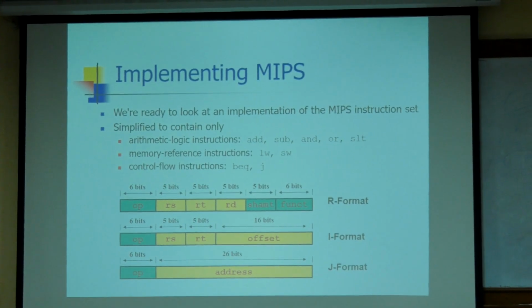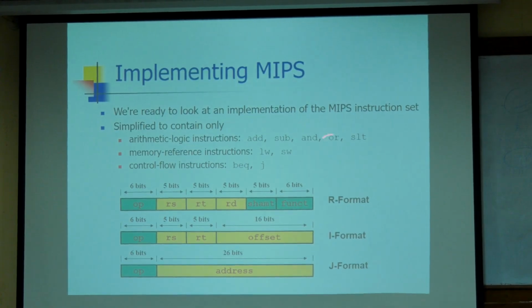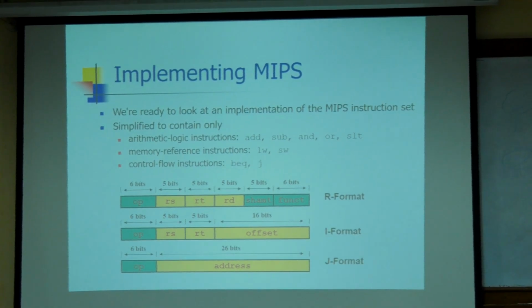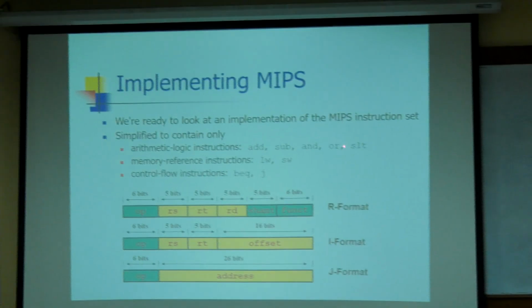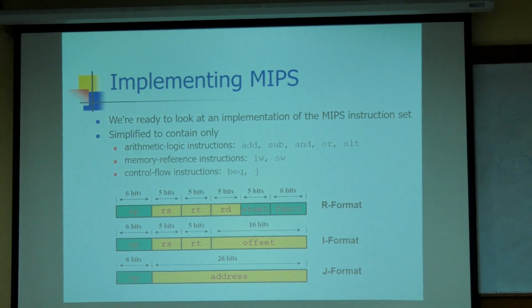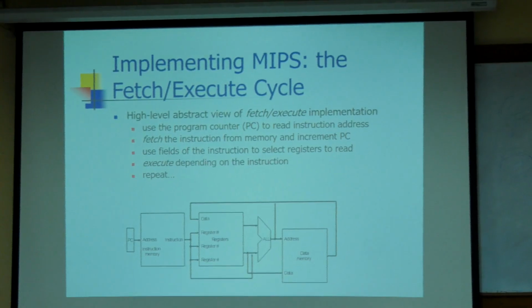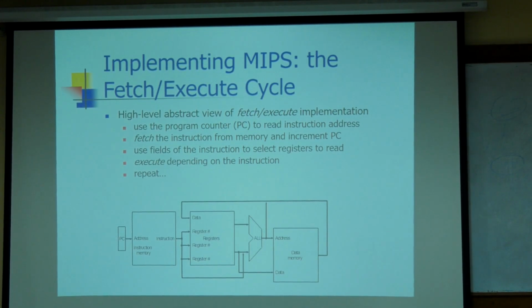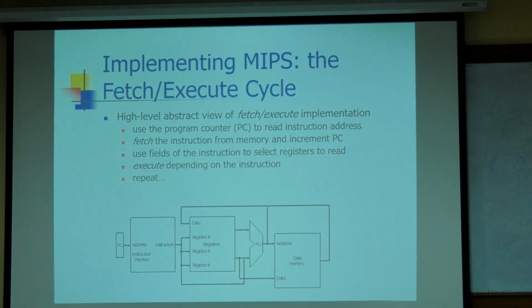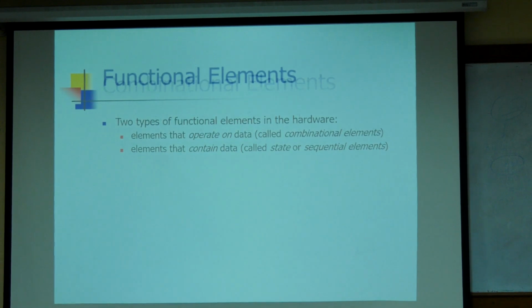Okay. So now to implement the data path, first we are going to design the data path to implement these instructions: addition, subtraction, AND operation, OR operation, compare operation. First we developed the register file, then later the program counter logic we also designed. The next is the R format instructions data path that we are going to see.